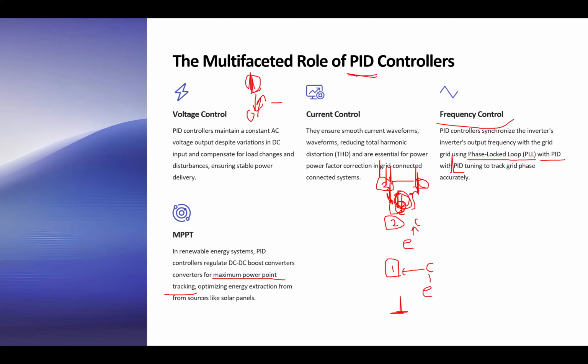All it does is calculate the error between the current value and the target value, calculate a specific correction, apply that correction, see how much closer we get to the targeted value, and if we need another round of correction, it applies that. It's a sequential real-time scenario that goes on and on to address the real-time variation.